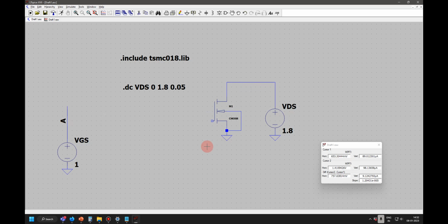Okay. Now one more thing which you need to remember is, see, I am drawing a line out here. I am putting a wire from here to here. I have drawn a wire, but that wire has actually not got connected to the gate. If it got connected to the gate, this square thing would disappear. So this is actually not connected.